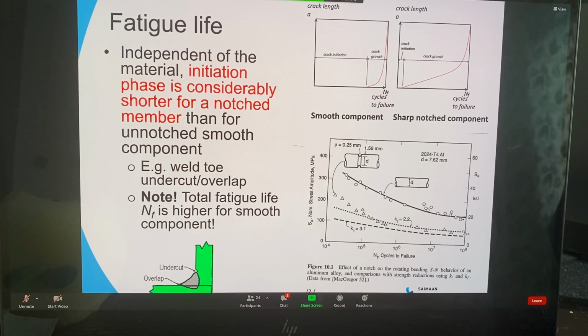Yeah, and in the situation where the crack starts, the mode is already one. Yeah, that also. So it's the worst case scenario when it starts there and the force is applied. That's also true. If you have a tensile or bending load in this vertical plate, it's already mode 1. That's also a good point.